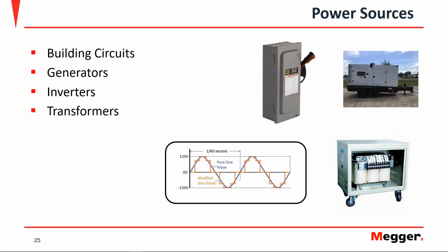But still, you want to make sure that you have a proper power source to energize your test instrument, either if you're turning off your building or facility circuit, or if you're using a generator or an inverter, especially. You want to make sure that generator or inverter has the proper power quality.